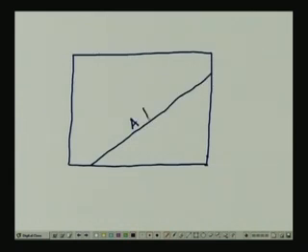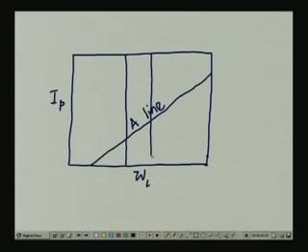So, this one is the A line, and what we are doing is plotting the plasticity index against the liquid limit, and I said that in case of the IS code you have got two vertical lines really at WL of 35% and WL of 50%.